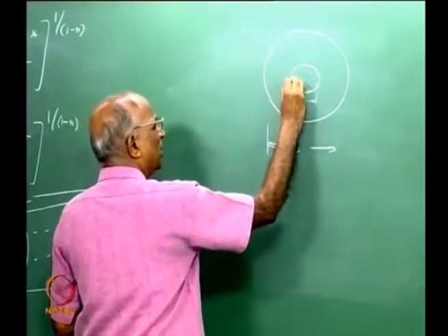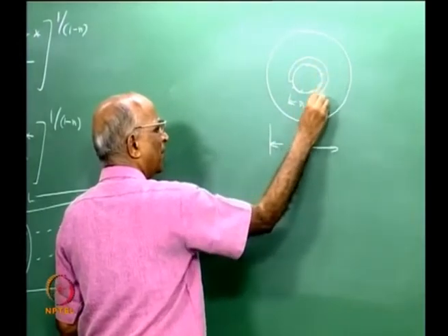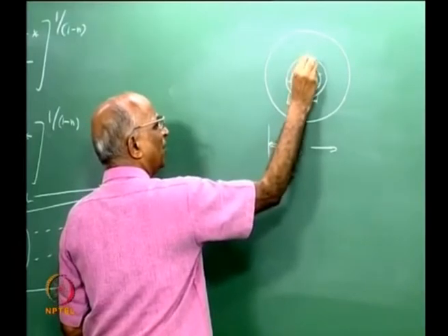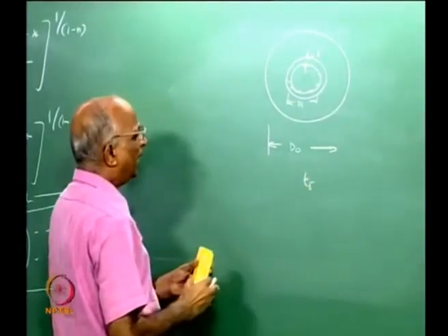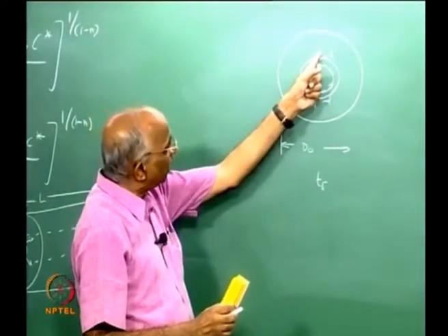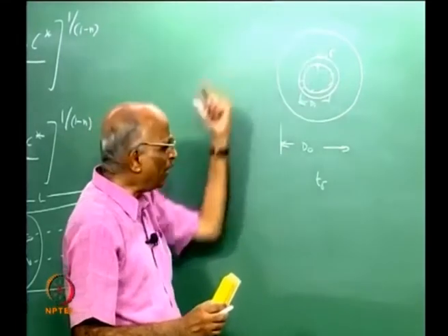Let us consider that a small part of the propellant gets burnt, and let the small part be of thickness delta over a time, let us say t delta, and then at the end of t delta I will calculate the pressure again, at the end of 2 delta I will calculate the pressure again, like that I can progressively calculate. And how do I do it?